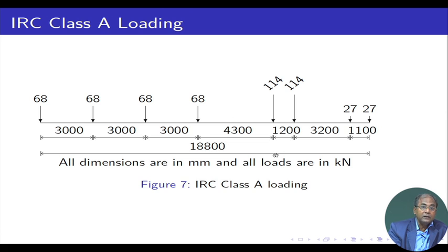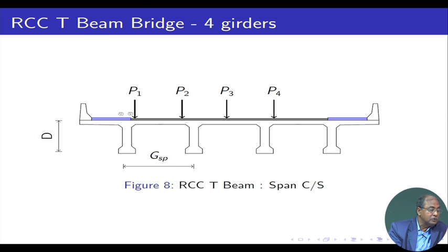So, this is the loading that we are having, and this loading is for the whole vehicles. Here, according to IRC 6, the combination, either I can have 70R loading only one, because for double lane we should have two. One IRC 70 loading, but for double lane we shall have this one here, that loading, that is for one, IRC class A loading, this is IRC class A loading.